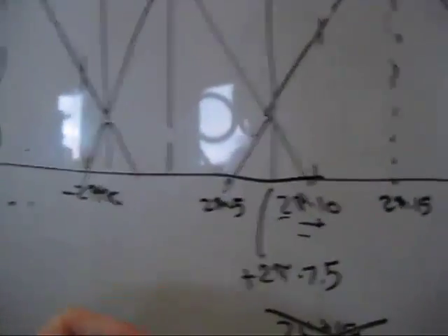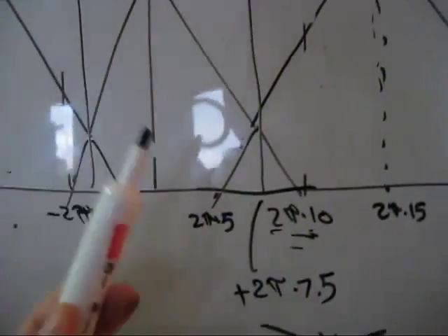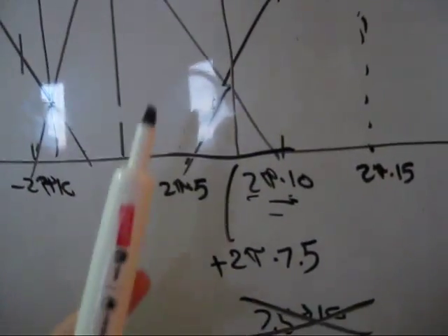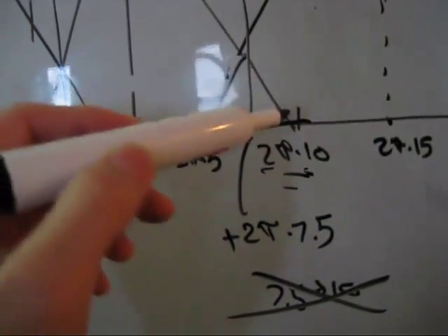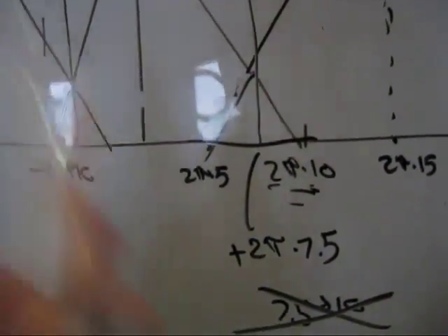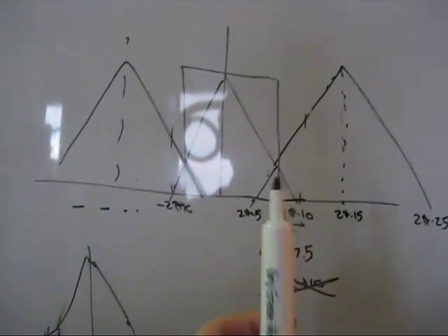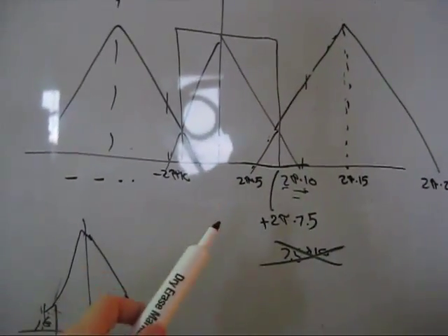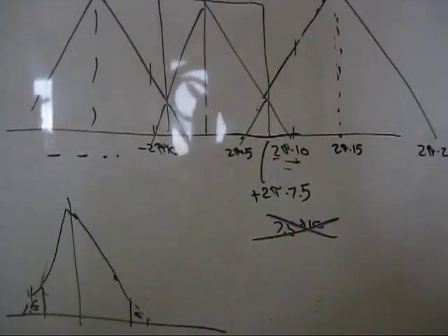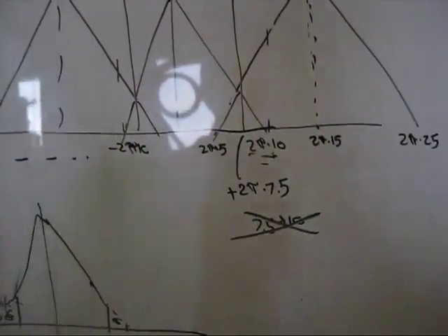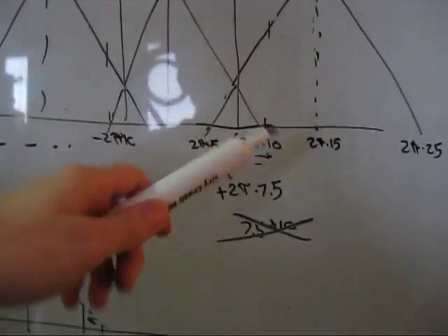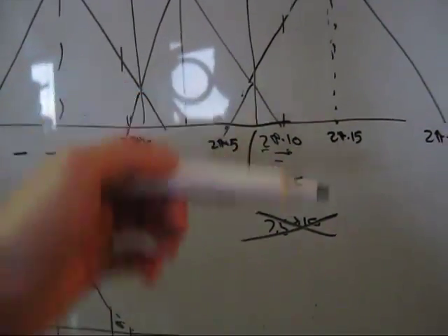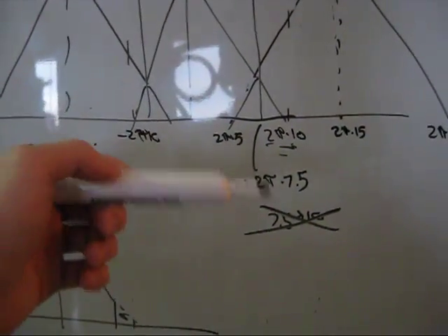So that's why for these signals you have to sample at least 2 times the maximum frequency that you have. But as we've seen, you don't always have to do that. The previous thing that I showed went up to 14 hertz, and we sampled at 15 hertz, and there was no problem.